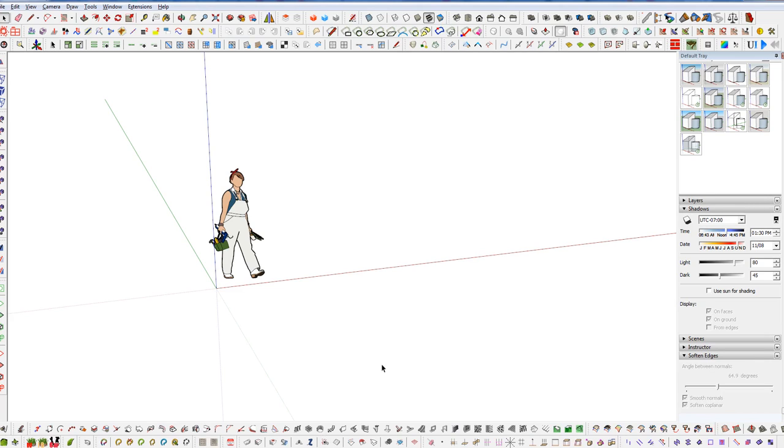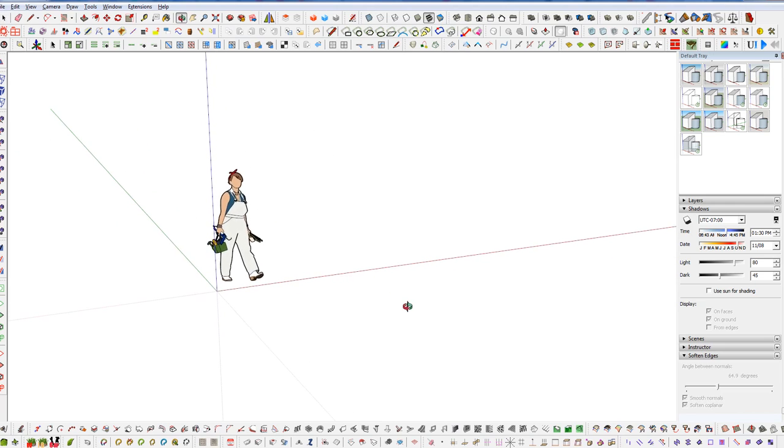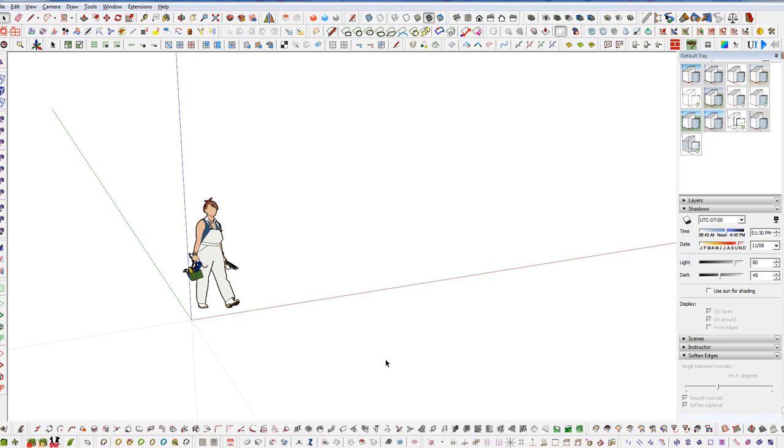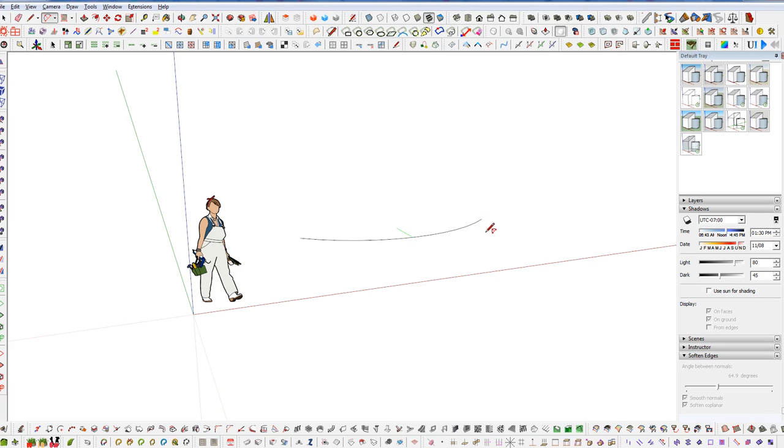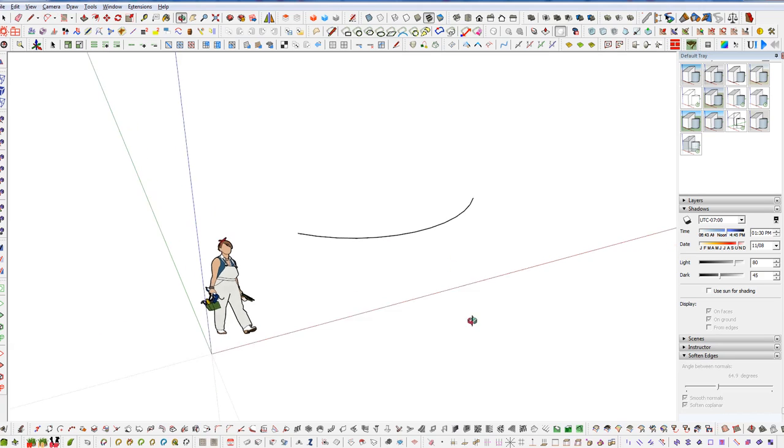The way it divides up your geometry and then deforms it to a target, so you have a source and a target, but it does it over a surface and not just linear. So this really opens up some possibilities and allows us to essentially deform or bend geometry in more than two axes. So as an example here, I'm going to draw out a curve.